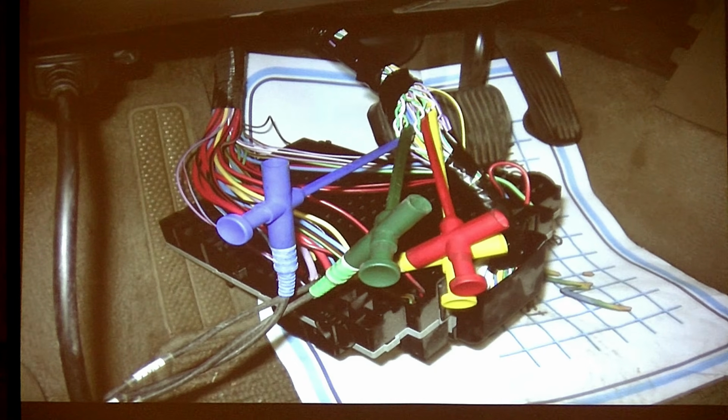To get this started, don't you have to have a security system? Now remember the Ford that we looked at that was ringing and the wires were broken on it? And it rang and I told you it started? I forgot to ask a question on that and I apologize. But I want you guys to think, why did it start if the bus is dead? That's because the anti-theft system sends a signal over a receive and a transmit directly to it. So the module is up on the steering column and it directly talks to that PCM. It's not on the bus. So it starts and runs.